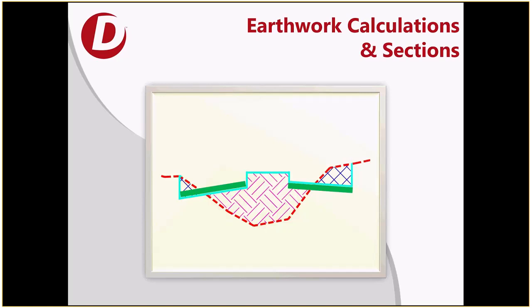Sometimes we have cement treated base. An example of that is on the left. That is an imported material, so it doesn't count as part of your earthwork. Sometimes we have processed in-place materials. Lime-treated subgrade is an example, where we're actually stabilizing the native materials. So that does count in the earthwork.